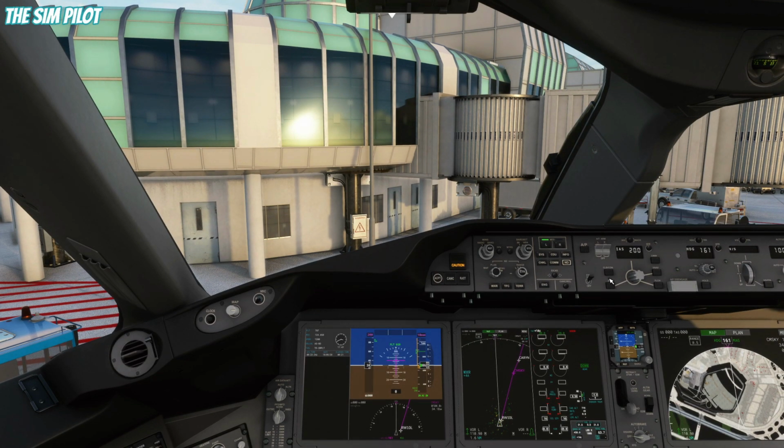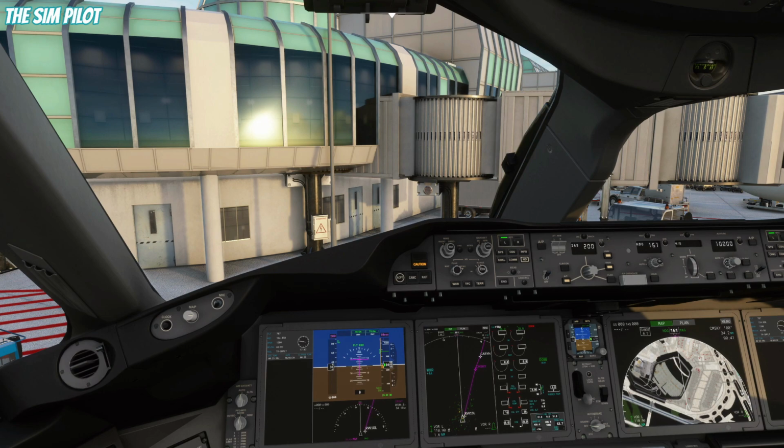Turn on the flight director. You can turn on LNAV, VNAV and auto throttle right now. We can set the cruising altitude to 37,000 feet, assuming we will be cleared all the way to our cruising altitude. Indicated airspeed can stay around 250 for now. There we go. And we will plug in the runway heading prior to departure, which will be, I believe, around 100 or 97, 98, something around those lines. I have to check the charts to be exact for those.